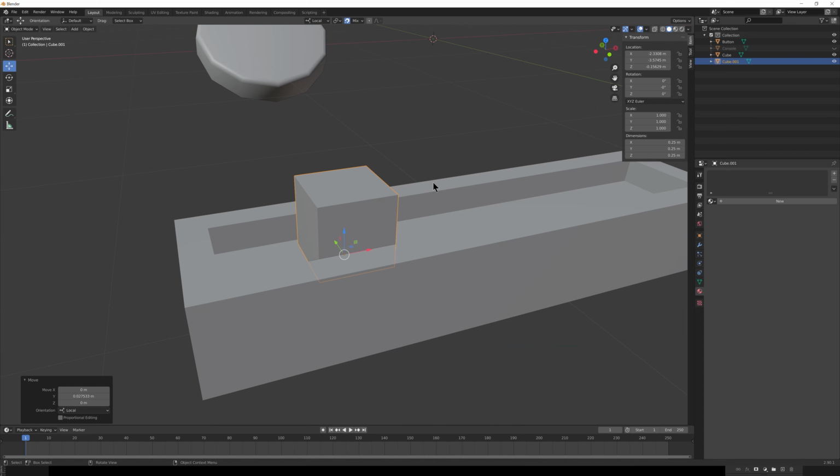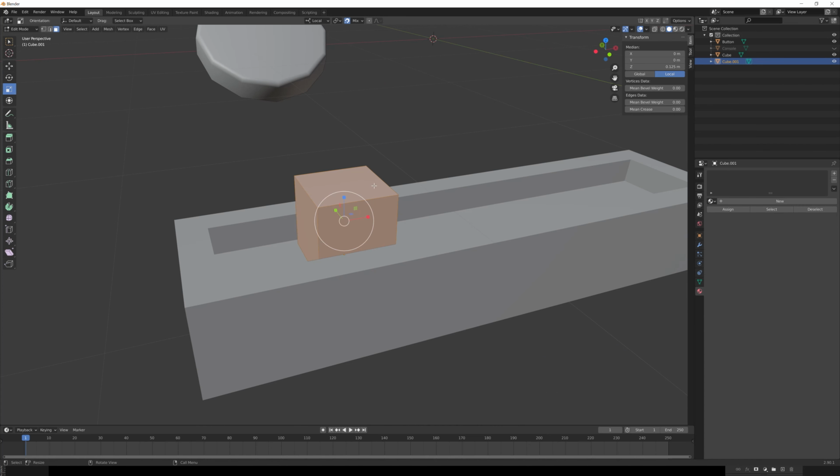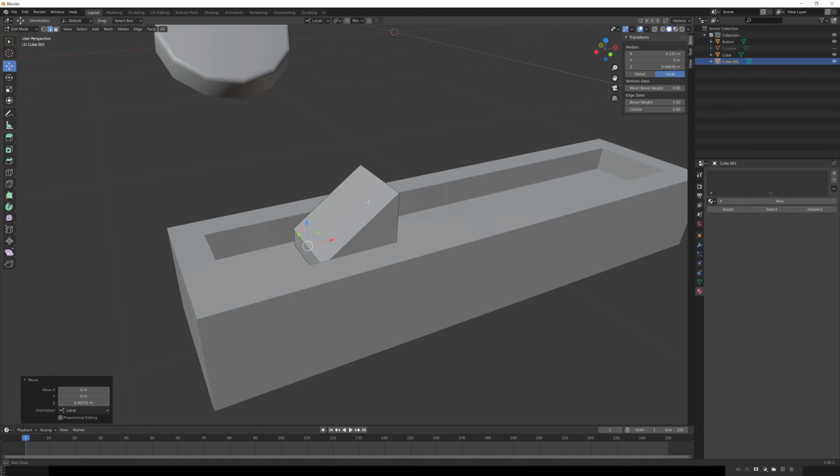I'm going to make this very simple. I'm going to hit the Tab key, and we're going to go to the edge mode by hitting 2, and then I'm going to hit Shift, Space, and then let's go to Move. I'm going to move this down to create a slider. Now I do have snapping on, that's annoying me, so I'm going to hit Shift Tab to get rid of that. And I'm going to move this somewhere along, maybe like that.